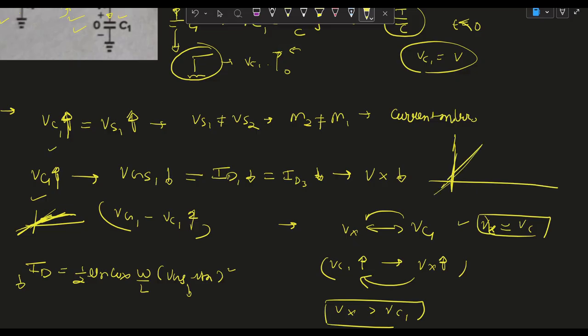I will make this much clearer here. Initially it will behave like a ramp, where this is the charging and this is time. But as current is decreasing, the slope of charging also decreases. Due to this, our voltage rise also decreases, and it will look like an exponential charge.